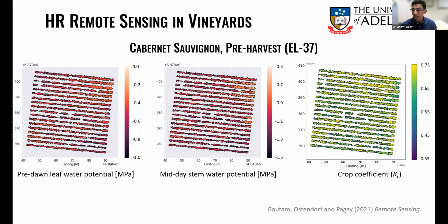And the crop coefficient, the Kc, is something that feeds into the evapotranspiration calculations. Here, each of those little nuggets, it may be hard to see, but each of those little nuggets are single vines. And so we can, across several hectares now, using UAV-based remote sensing with the right types of cameras, multispectral cameras and thermal cameras, start to get an indication of the spatial variation in these parameters to inform the placement of proximal sensors, such as those tensiometers or towers or sap flow sensors or what have you. So understanding the spatial variation is really critical to start to optimize irrigation.